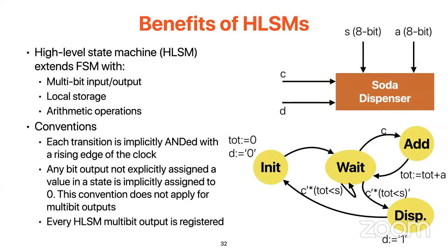Okay, Fox, do you have anything that you want to add? Yeah, I wanted to add that state and stored data are fundamentally both information. They're both stored as flip-flop information. States are just enumerated in a table, and then the synthesizer will figure out the best encoding, or you can by hand. But ultimately, the reason why I say HLSMs decompose to FSMs is because if you were to just look at the gates themselves, it's actually kind of hard to tell the difference between the storage registers and the state registers.